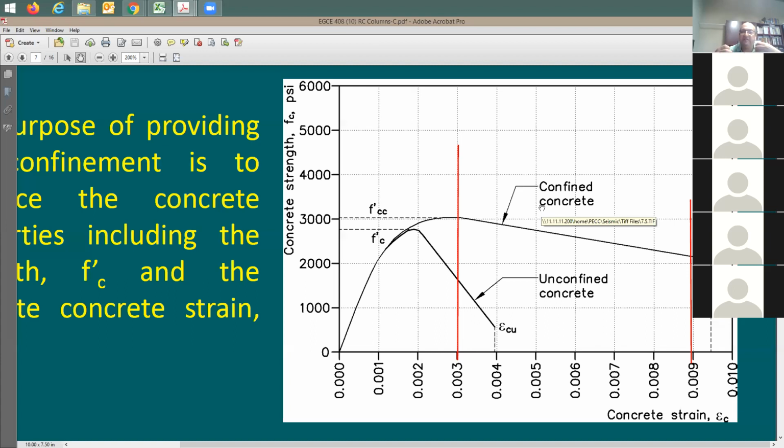Now, how much is the stress that you're going to have in each one of the specimens? You're going to say it's the same, because you take this 1 pound divided by the cross-section area of the specimen or sample, and it gives you the same stress. So the stress within the sample itself or the column is exactly the same. This is the stress that you develop from putting on this load.